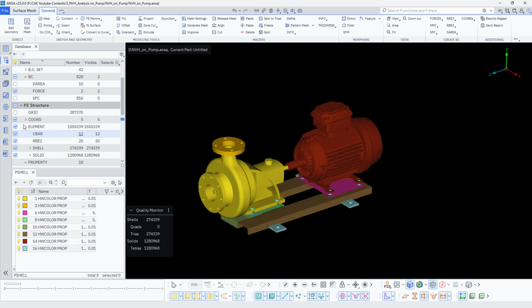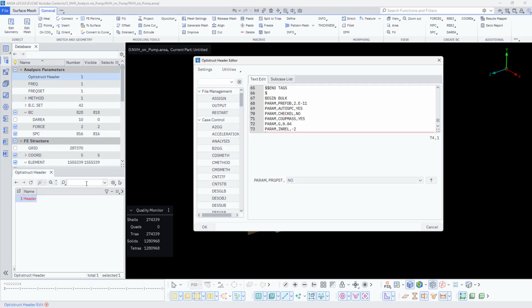So let us see now. Yep, just simply cross verify. The moment of inertia relief method is there, I'll just remove it because I have the SPC model in it. So structural, I can consider that. If you want, you can remove some of these param cards, but I keep them for all the analysis defaults, so I'll just simply keep it. If something is not needed, the solver will show that this is not required. It will show in the form of a warning.